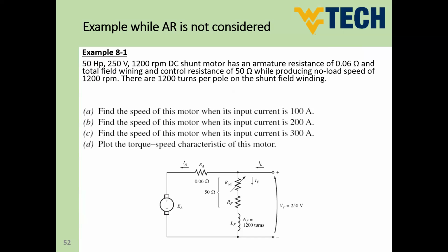But again, we discussed before that DC generators are obsolete. We don't use them anymore. So if you find the two nameplates available on the machine, neglect the generator one and just consider the motor one. So 50 horsepower means the output power. All of the time, guys, the power given on the nameplate is the output power. So 50 horsepower here is representing P_out. So we can say that P_out equals 50 horsepower.